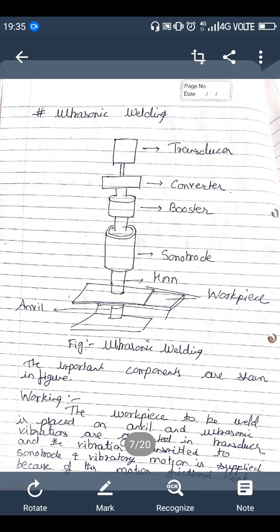Because of vibratory and oscillatory motion, frictional heat is generated on the contact surface, and the molten metal flows into the joint surface. Melting rate increases, resulting in increased weld displacement, and the part surfaces fully meet. The horn gets retracted, and the welded material can be removed from the anvil.